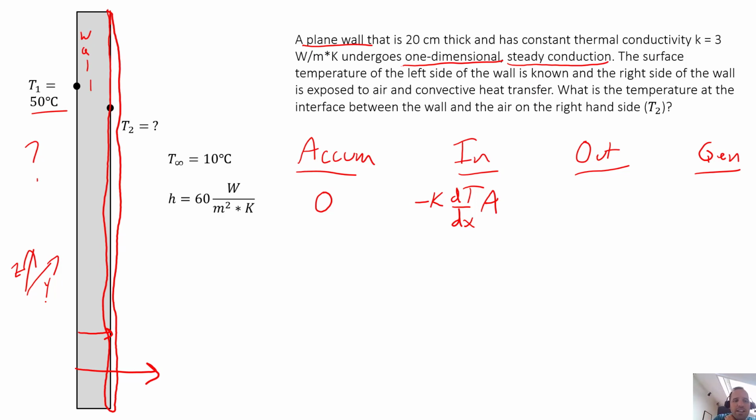Okay, so energy is getting into our wall, into that very interface. We'd want to measure what the derivative of our temperature with respect to x is right at that interface, or right at x equals L, with L being our wall thickness, which I have just now defined.